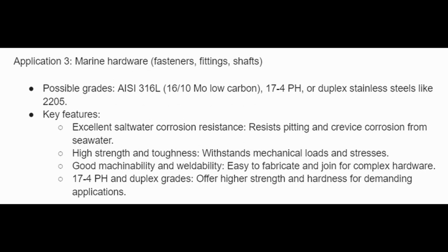Application 3. Marine hardware. Fasteners, fittings, and shafts. Possible grades 316 or even duplex, for example 2205. Key features. Excellent saltwater corrosion resistance. Resists pitting and crevice corrosion from seawater. High strength and toughness. Withstands mechanical loads and stresses. Good machinability and weldability. Easy to fabricate and join for complex hardware. Duplex grades offer higher strength and hardness for demanding applications.